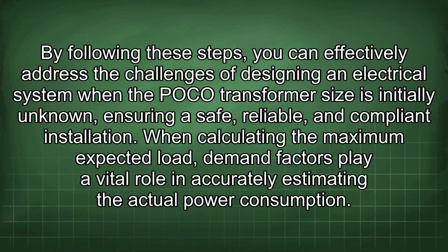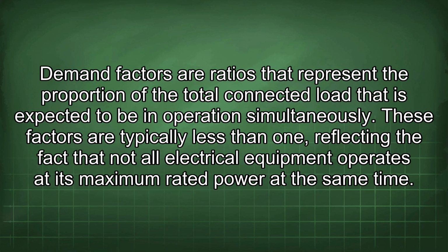When calculating the maximum expected load, demand factors play a vital role in accurately estimating the actual power consumption. Demand factors are ratios that represent the proportion of the total connected load that is expected to be in operation simultaneously. These factors are typically less than 1, reflecting the fact that not all electrical equipment operates at its maximum rated power at the same time.